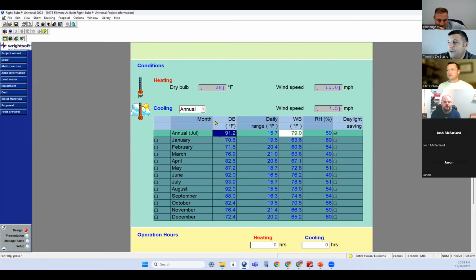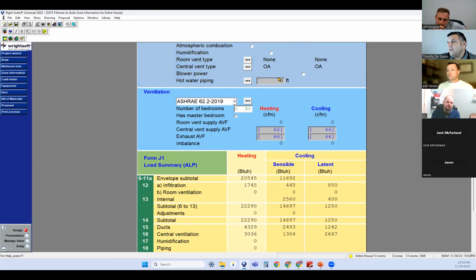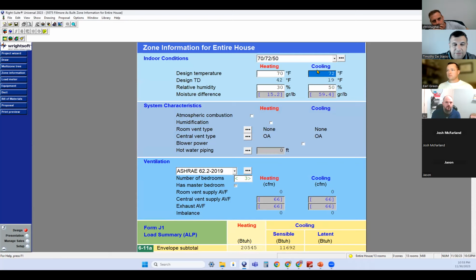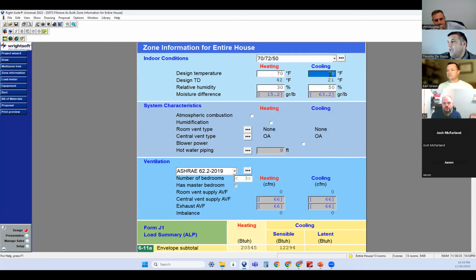Yeah, now I do want to show you guys something that really does drive the needle. Let me put this back. What if we were to say, instead of running at 75 degrees, let's make it 72 degrees. Oh, indoor temp? Yeah. Or actually, let's make it 70 degrees. I had just as much of a jump there. I went from 1.7 to 1.9 trying to cool the house. Yeah, indoor temperature matters more.